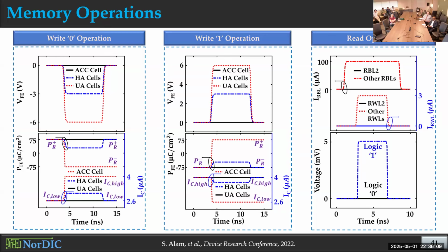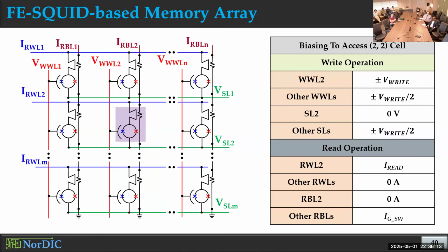So we need that, but here we also designed the memory array in a way that the current cannot be divided, right? So when we try to apply this current through one branch, we made sure that the current flows through that branch and doesn't go to other branches because of the superconducting nature of heater fraction. Because if we have two resistance states, the current can be divided. But here we have completely 0 resistance state from some heater fractions. Right. So that will take the whole current. Peripherals. And I'm probably getting ahead, I apologize.